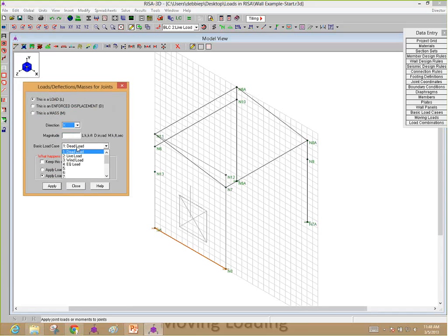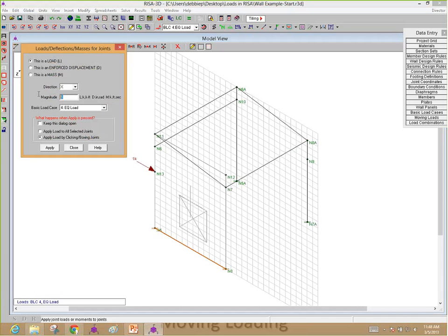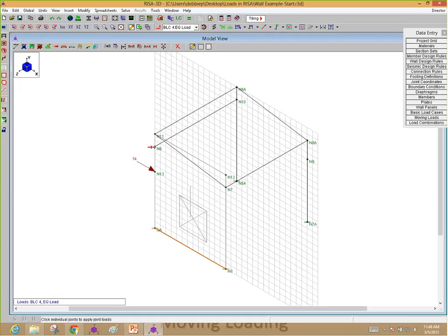So we'll say this is going to be our earthquake load, and maybe a kip in there at that funny load there. But maybe let's put some bigger ones in the top where maybe the rest of the structure frames in. So I can put that in up here. So you can put joint loads anywhere, which makes it nice. And I've got a collection of different loading. We see that again here.